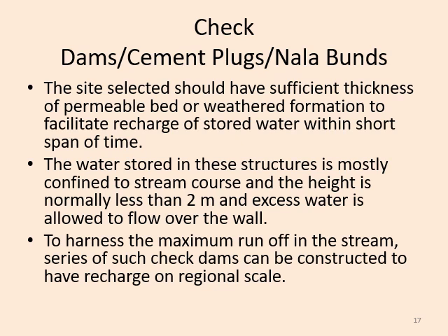The water stored in the structures is mostly confined to the stream course, the stream path, and the height is normally less than 2 meters. The check dam or the bund height is less than 2 meters, and excess water is allowed to flow over the wall. In Himachal also we have seen some check dams or nala bunds in some narrow streams or nalas, or in khads also.